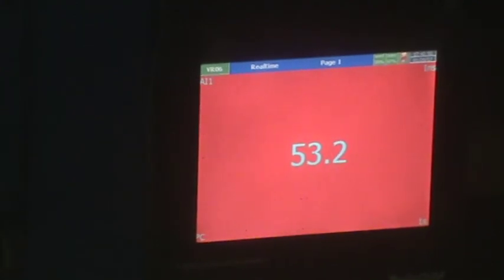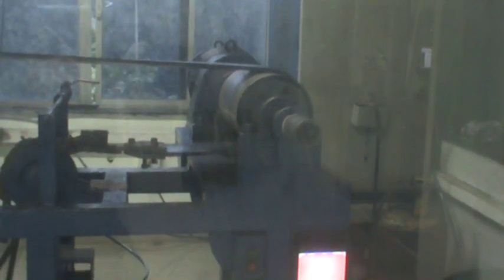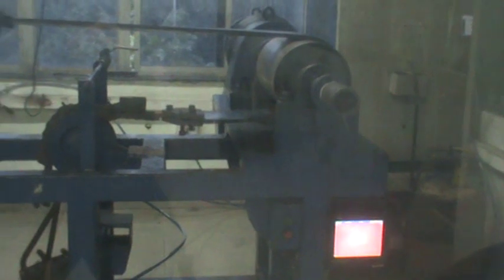F. Drum friction testing. The ability of a conveyor belt to resist burning and sparking as a result of being stuck on a conveyor system where the belt is not moving but the drive pulley continues operating can be measured using a simulation on a drum friction testing machine. In this case, the temperature of the belt is recorded over a period of time as the pulley continues to rub on the belt. Therefore, the units recorded are degrees Celsius. Depending on the standards used, the temperature is not allowed to go above a certain set limit.